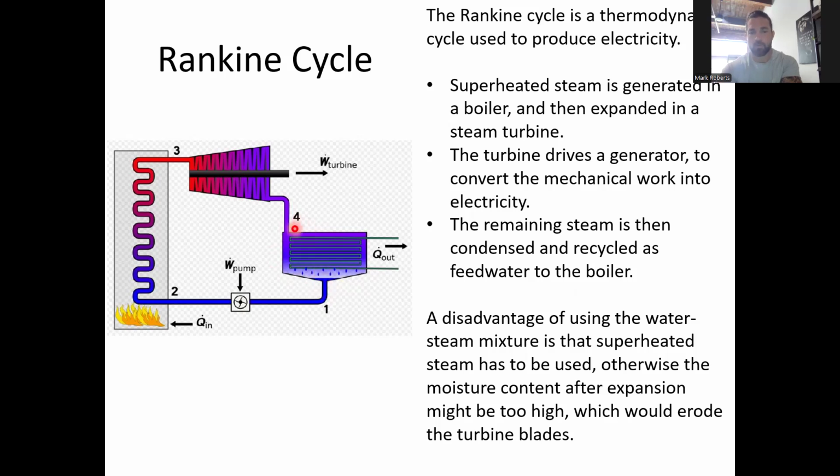liquid or potentially cooled liquid, but generally like a saturated liquid. And then this saturated liquid is pumped. So I'm not going to say compressed. It's incompressible, but the pressure of the liquid is increased by using a pump. So we do work on the process by a pump. And so because it's incompressible, it takes very little amount of work in order to pressurize the liquid from like a low pressure, like an atmospheric pressure, up to something that's